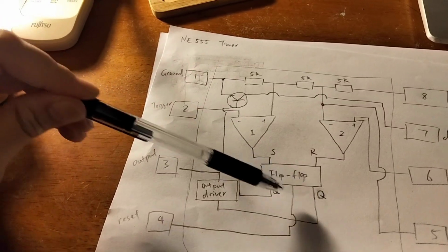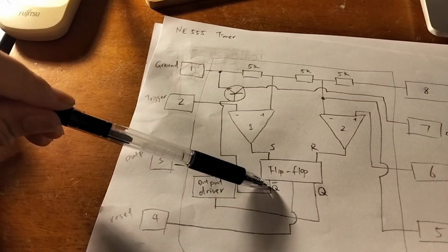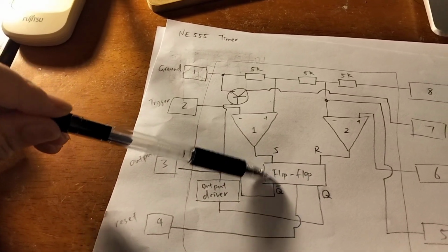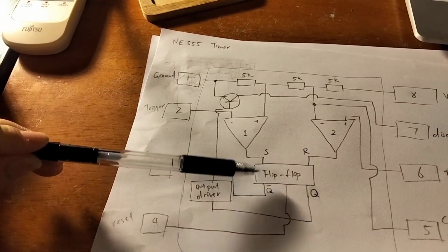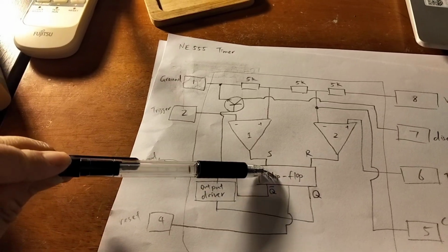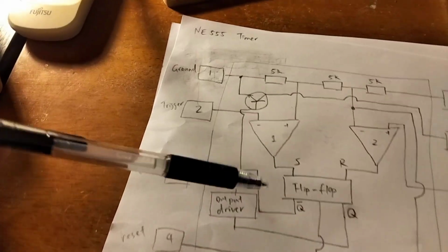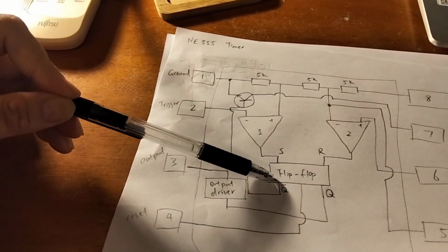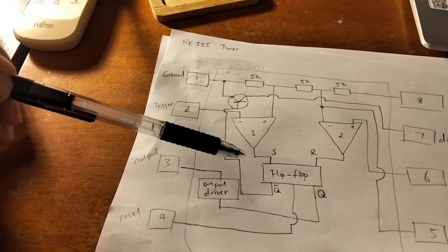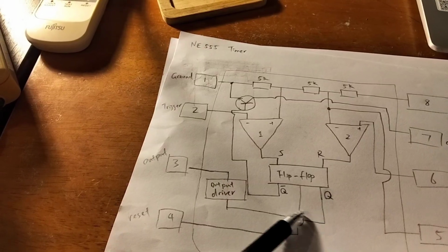And this Q and inverted Q output is basically one high and one low depending on the internal state of the flip-flop. If the flip-flop is 1, Q will be high and invert Q will be low, and if the flip-flop is low, then Q will be low and invert Q will be high. So there's a state being stored here based on what it was set previously, and this Q output is put to the output driver,